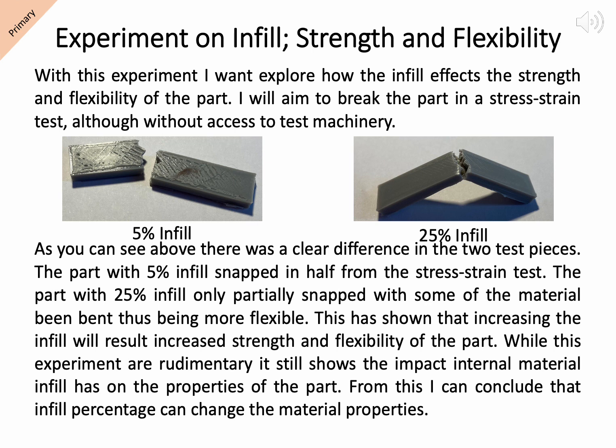The second experiment I conducted was on the strength and flexibility of these parts. I took the two previous specimens with 5% infill and 25% infill. I tried to break them in the same way a stress strain test would in a laboratory. Fortunately, I don't have access to that machinery, so I snapped them in half, or attempted to. The 5% infill snapped in half, while the 25% only partially snapped, with half the specimen still being attached. This showed how the different percentage infill affects the flexibility and the strength of the part, and in this case, the 25% infill won.